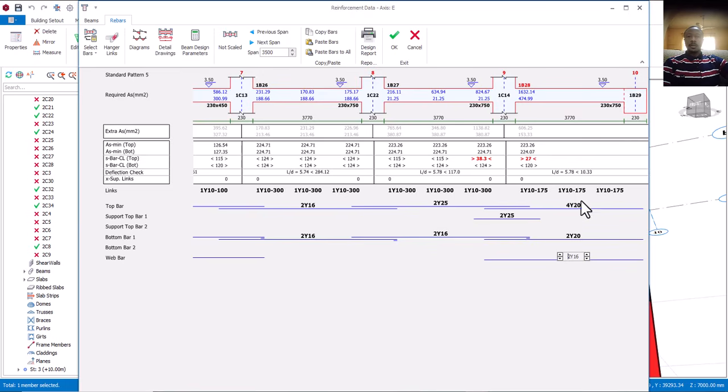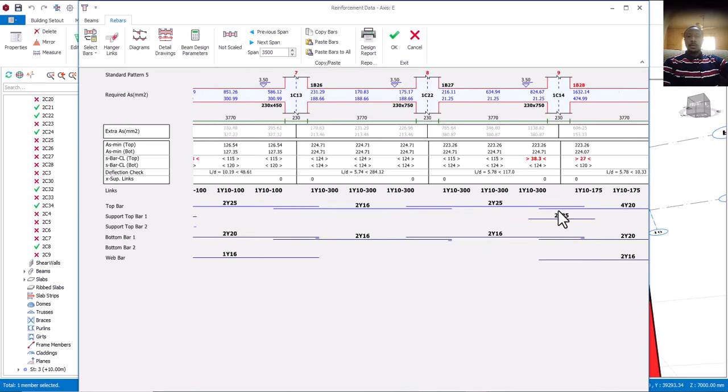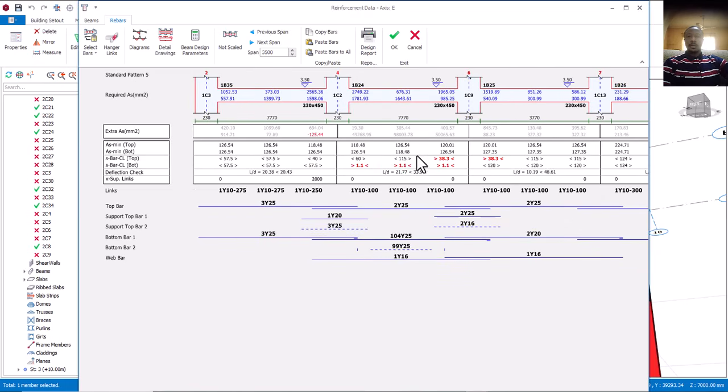Is that okay? So this is how to go about your selection of members and making them to pass. All of this, we have done videos on how to make adjustments. If you look at this, these are unnecessary reinforcement. Can you see why we are having this number of reinforcement? Because if you look at this beam depth for this 7 point span, it should be around 8 meters. Is that okay? 8 meters, and 450 beam depth can never pass. That's why we are having this bogus, unnecessary kind of reinforcement.